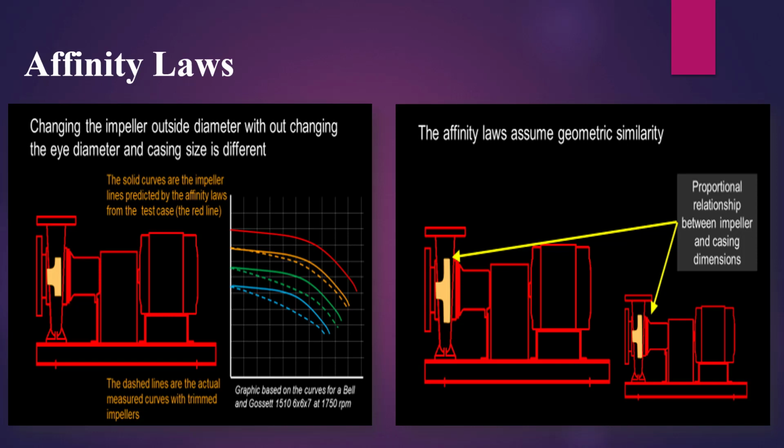Now is where it gets interesting for us. Power is proportional to the shaft speed, cubed. Half the shaft speed uses 1/8 of the power. Let's see that calculation. Imagine you have a shaft speed of 10. 10 cubed is 1000, 10 times 10 times 10. Now let's take that speed down to 5. 5 cubed is 125. 5 times 5 times 5. Half the shaft speed, 1/8 of the power.